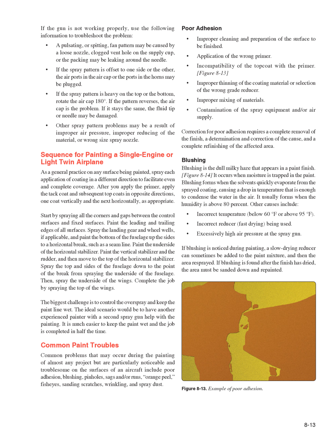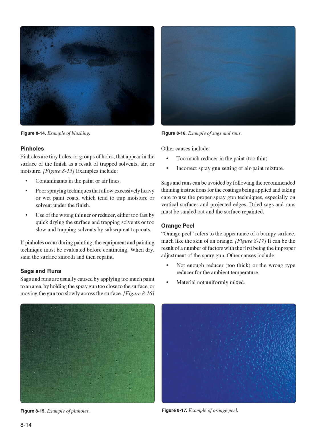If blushing is found after the finish has dried, the area must be sanded down and repainted. Pinholes. Pinholes are tiny holes, or groups of holes, that appear in the surface of the finish as a result of trapped solvents, air, or moisture. Figure 8.15, examples include contaminants in the paint or air lines.